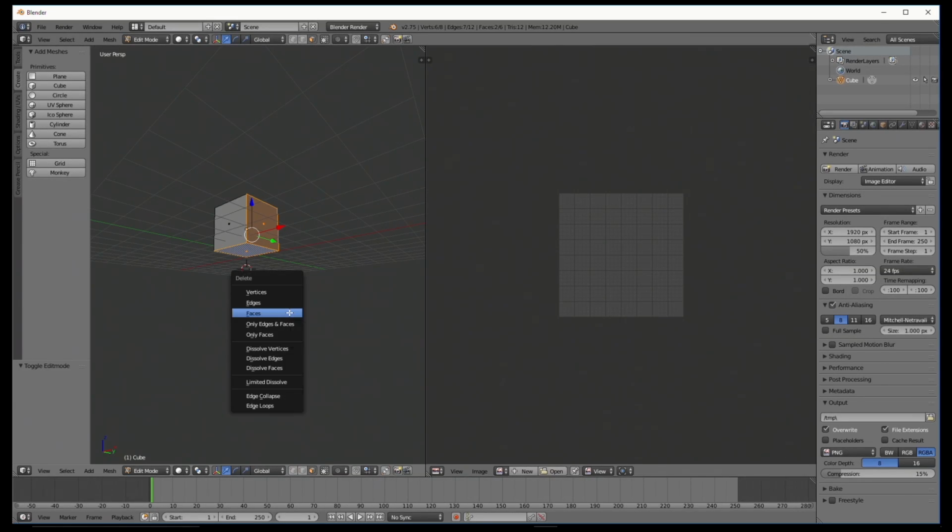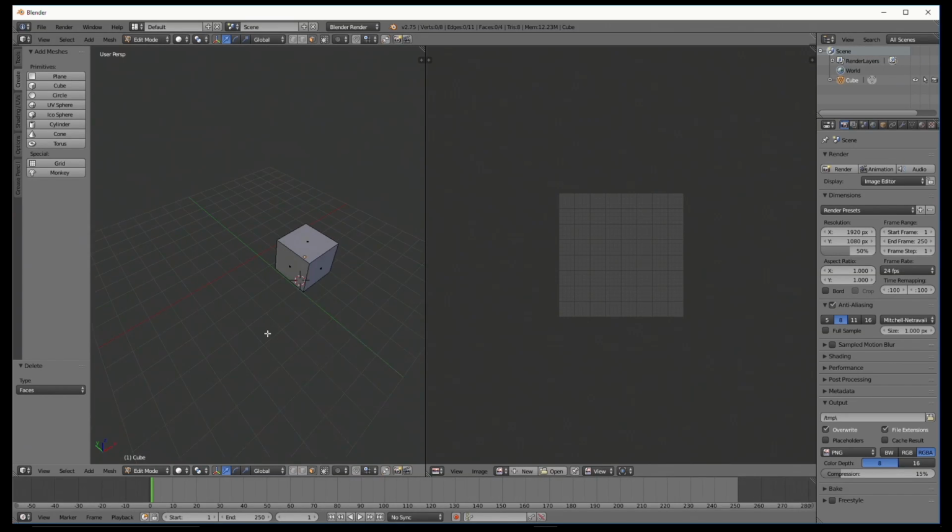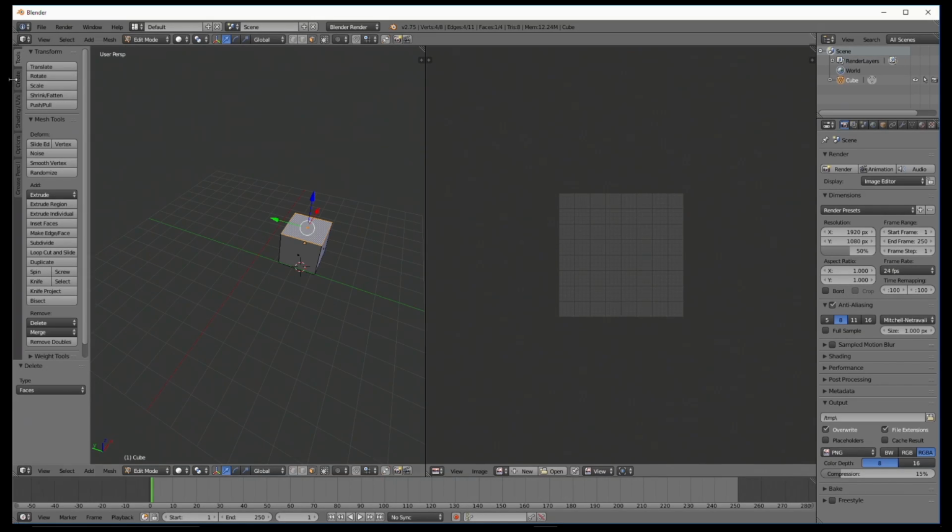Okay, so I think we should give this a few more angles, make it a little bit more interesting. So I'm going to select my top plane, my top panel. I'm going to, on my Tools tab, double click Scale. If you remember, if you click it once, then it will lock to the mouse, but if you click it twice, you actually get a number box down here. So I'm going to put that down to 0.5 by 0.5, like so.